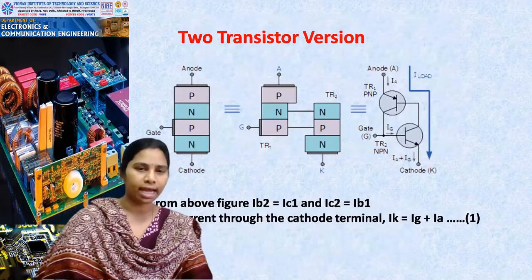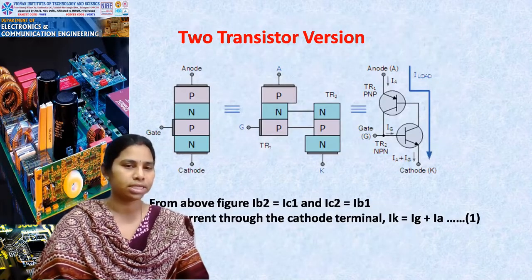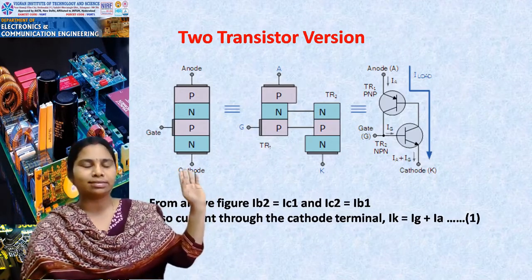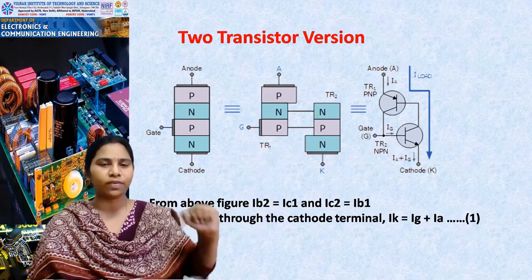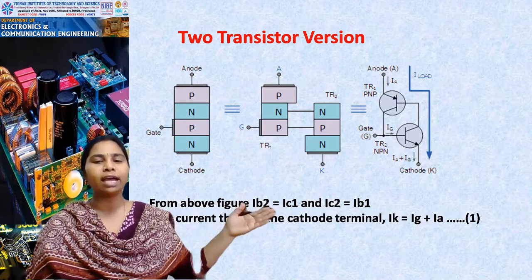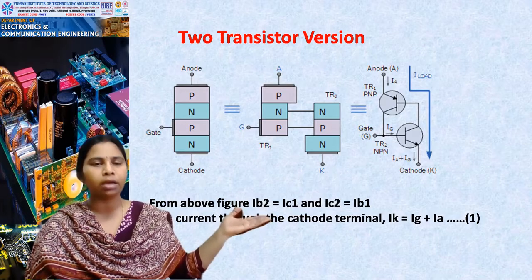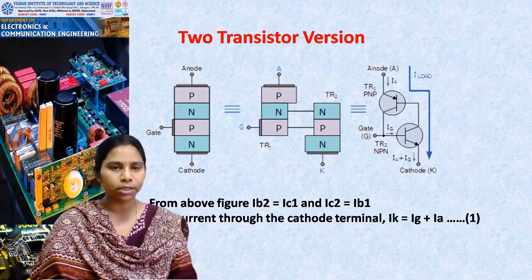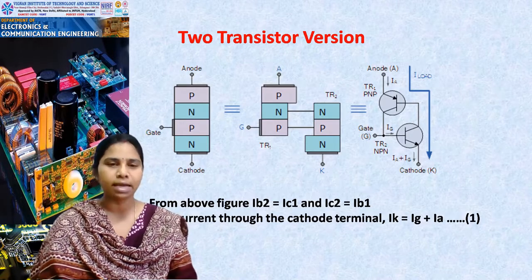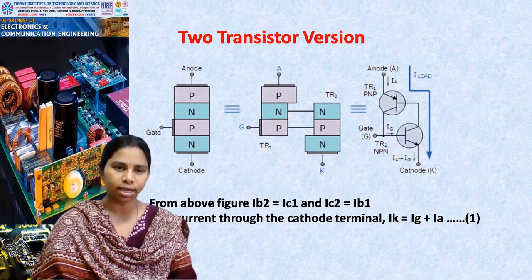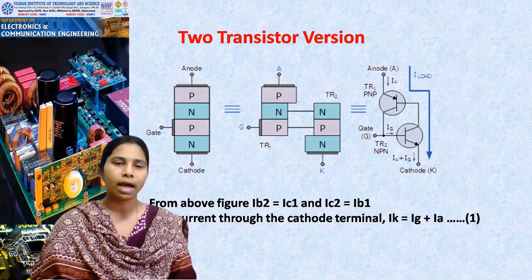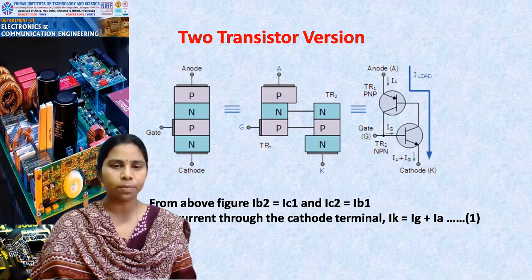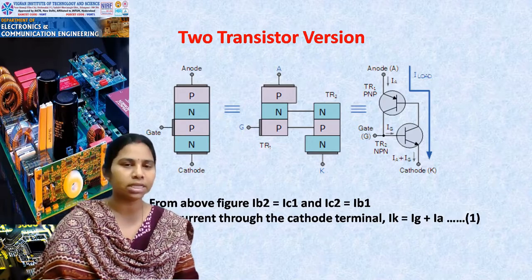If you want to derive the current through the silicon controlled rectifier, you treat them as two transistors connected, where the collector is connected to the base of the other transistor, and you are able to derive the equation of SCR anode current with the basic transistor equation, IC is equal to alpha IE plus ICO. ICO is the reverse saturation current. In the place of input current, you take IA, the anode current. IE is replaced with IA. The rest of it is the same.